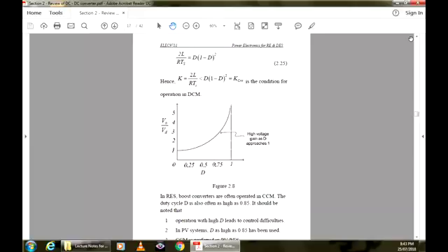And in the industry, D has been used as high as 0.85, which gives you about 5 to 6 times the output voltage. But then it is difficult to control, and the challenge for design of the controller is quite high. But that problem has been dealt with.